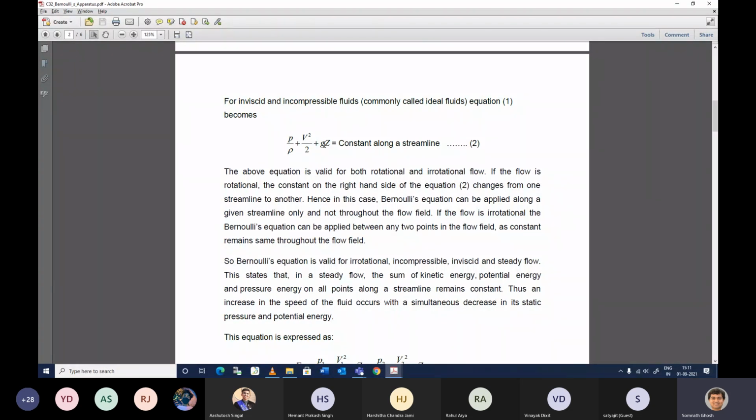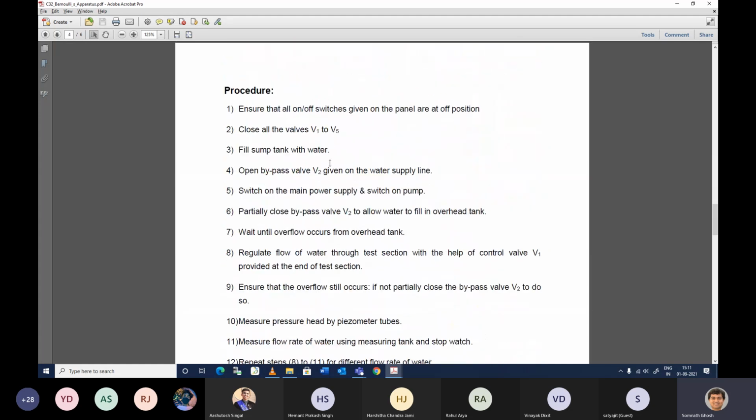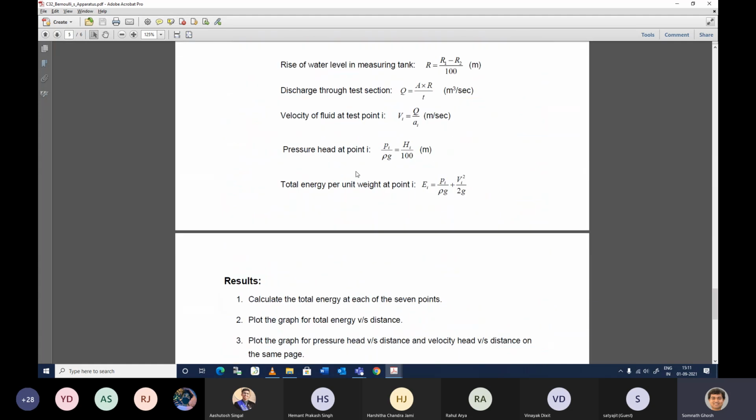In this experiment you don't have any elevation, so you can neglect the potential energy part. You just need to work with the energy at any given point, the energy due to the pressure component and the velocity component. The velocity you get from the volumetric flow rate, which you measure in the experiment. Essentially, you are not doing the experiments, but those data will be provided to you.